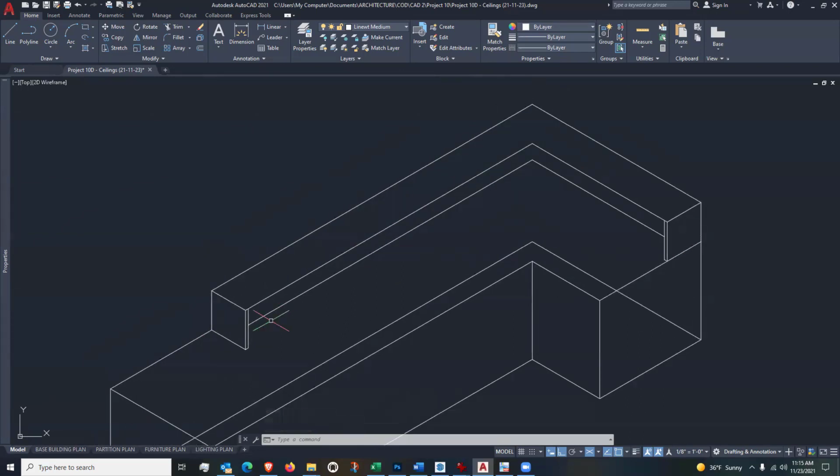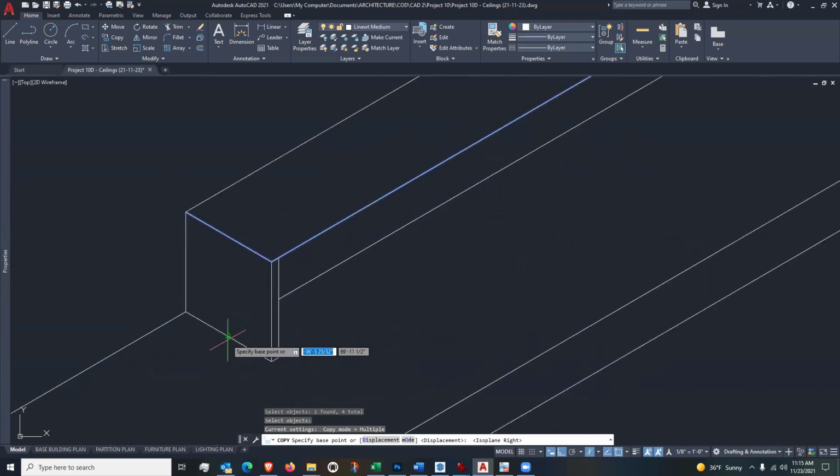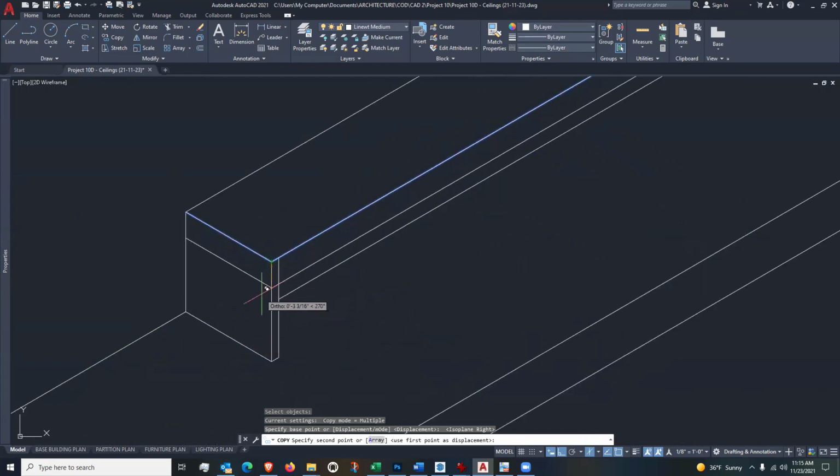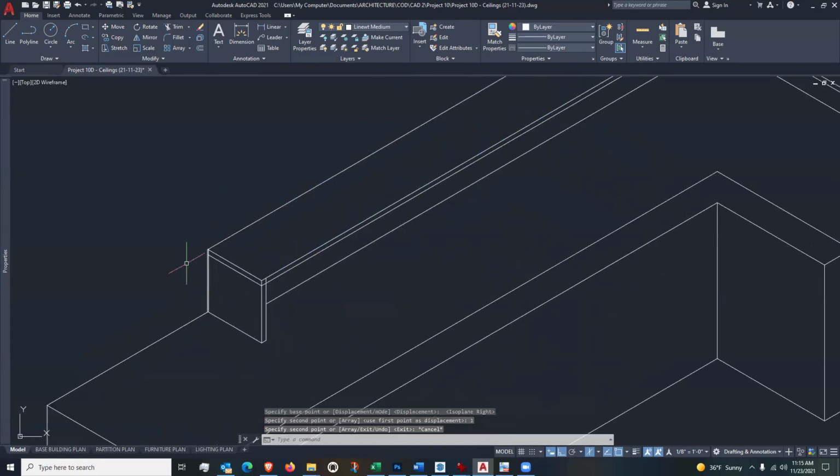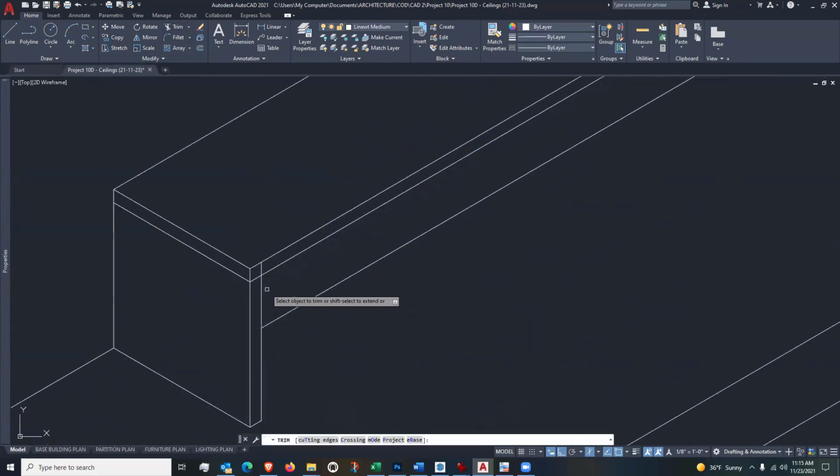And let's draw the thickness of the transaction top, which is 1 inch. So I'm going to just copy these surfaces or these edges, and I'm going to copy them down. So I need to change my isoplane so I could go down just 1 inch. And then let me do some trimming here.